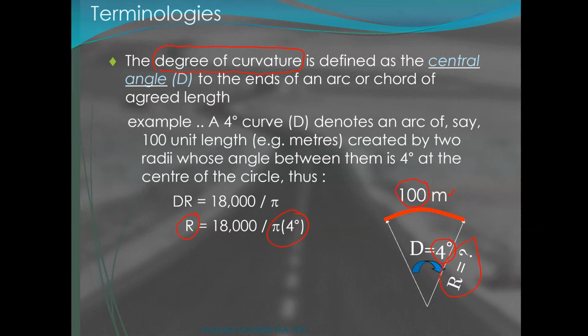Degree of curvature. So when I say a 10-degree curve, immediately you understand that it's 10 degrees at the center, 100 meters long, the arc length, so we have to find out what the radius is.